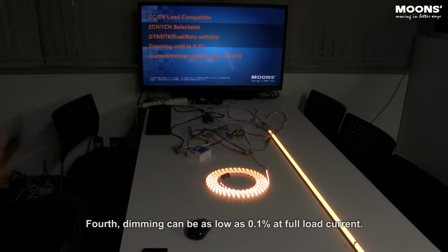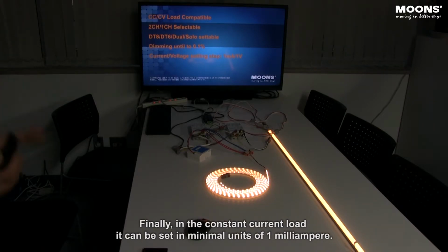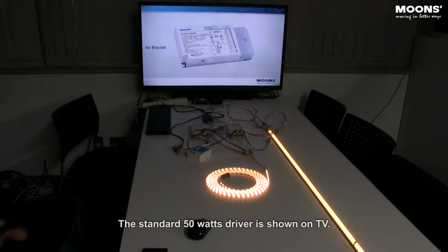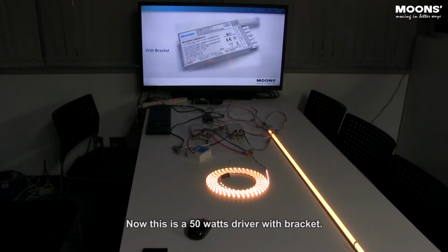Fourth, dimming can be as low as 0.1% at full load current. Finally, in the constant current load it can be set in minimal units of 1 mA, while in the constant voltage load it can be set in minimal units of 1 volt. The standard 50 watts driver is shown on TV. Now this is a 50 watts driver with bracket.